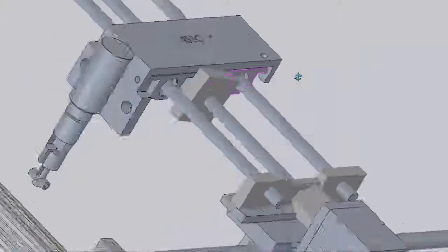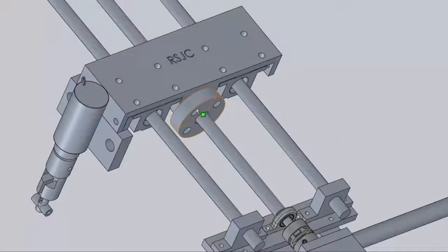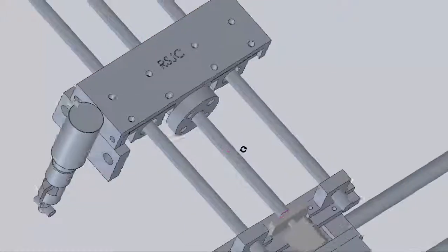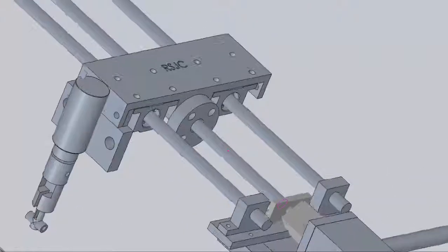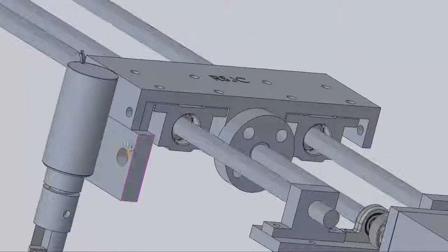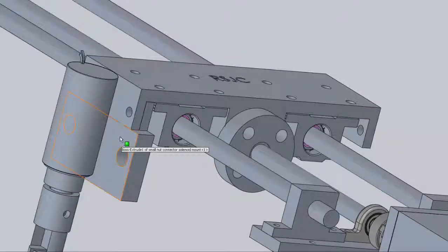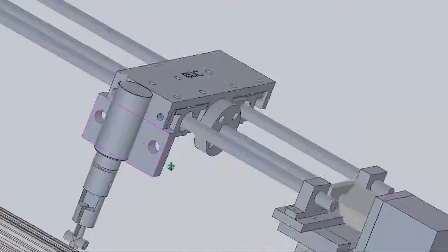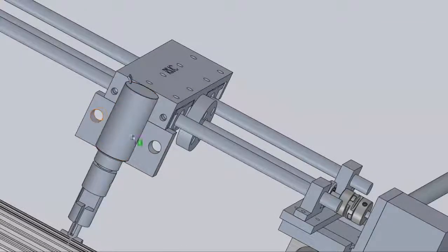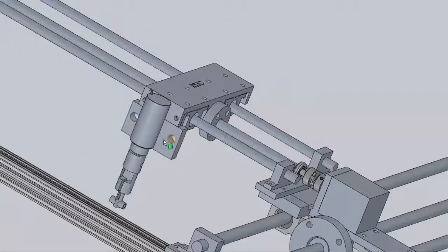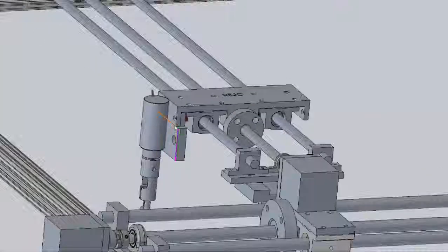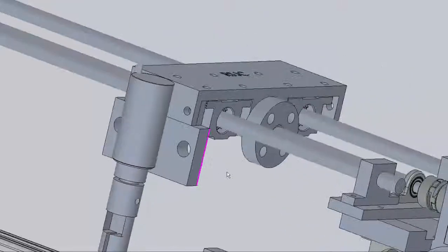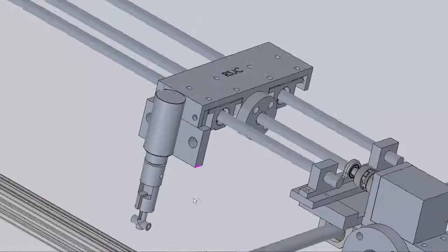So we can see the small nut connector here. It's connected to the flange in the same way as the large nut connector and to the linear bearings. There's another 3D printed part here. This is temporary until we finalize the design with the actual 4 probes that will go in the live product. The solenoid can be connected via a U-bolt to the small nut connector in this secondary 3D printed part, which is attached through this hole here. So it is held perfectly vertical to the surface.